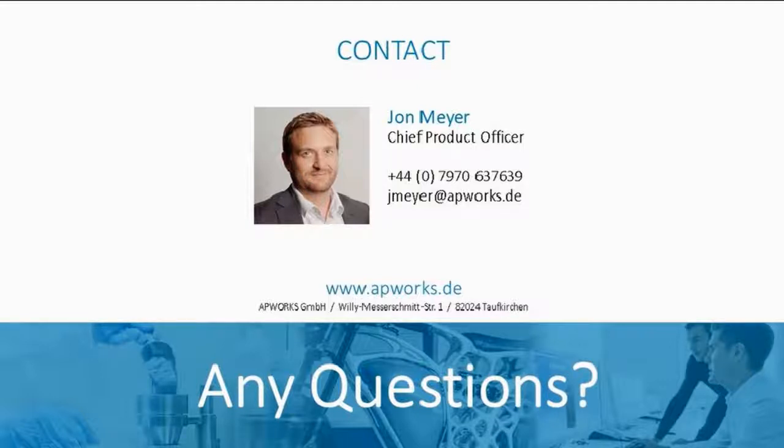There have been some very interesting developments, for example, in GE Avio, which was acquired by GE, on titanium aluminides, which process very well using electron beam powder bed fusion, so a slightly different metal powder bed fusion process. And those alloys are very interesting. A lot of work has also been done in the UK on things like Hastelloy X. As always, it takes time for them to get through to, say, rotating part critical applications as opposed to static things like exhausts and so on, which they're already used extensively on.